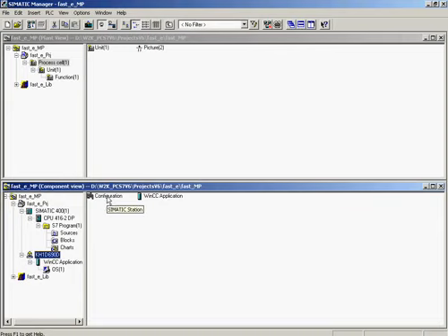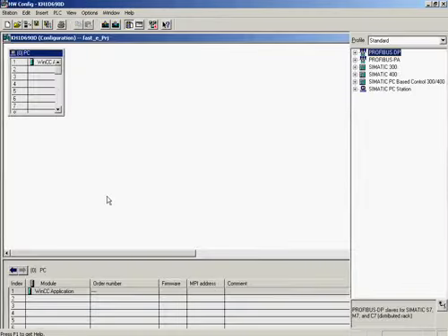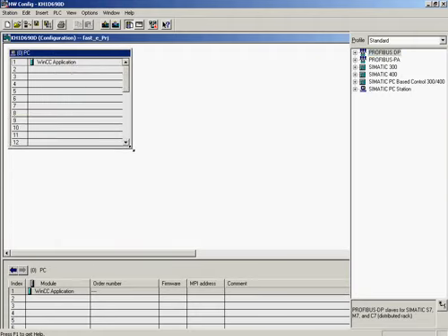Now the computer is configured with hwconfig. This integrated part of PCS7 allows you to configure PC stations and automation systems. The configuration is carried out according to the previous basic PC configuration in what we call the Station Configuration Editor.